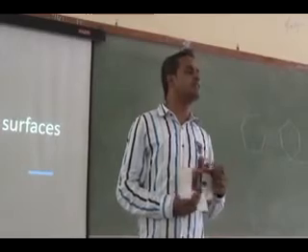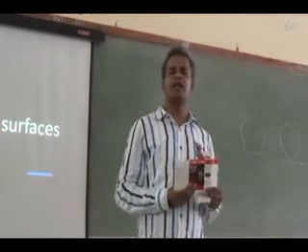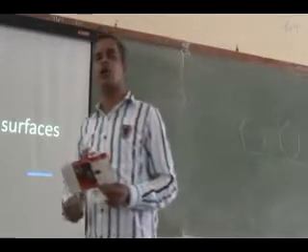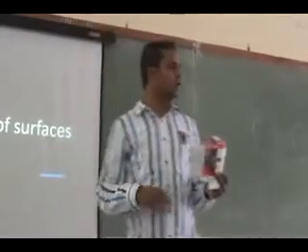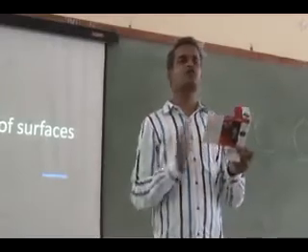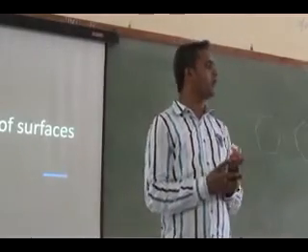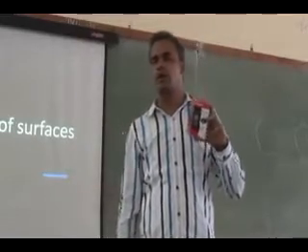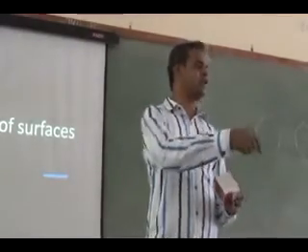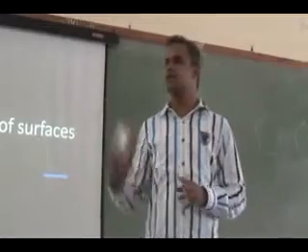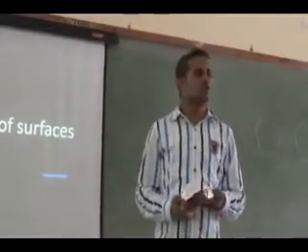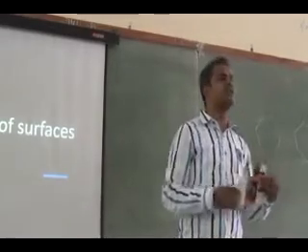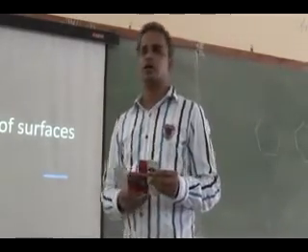To avoid wastage of material, if we know the exact development of a component, I can draw and cut that alone, fold it, and then weld it or rivet it to make the required component. So to avoid the wastage of material, we need to study the development of various solids.